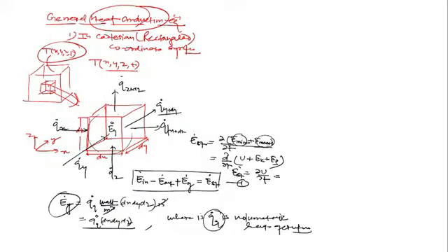Is this clear? And u is what? It's the internal energy of the system. Also I told you that in the case of solids and liquids, Cp or Cv, whatever you connect, they are equal. For incompressible substances, Cp and Cv are equal. I told you, yes or no? Cp and Cv only have meaning for gases, but for incompressible substances there is no distinction. Otherwise the value is only m Cv dT. Clear beta? I told you du equals m Cv dT.